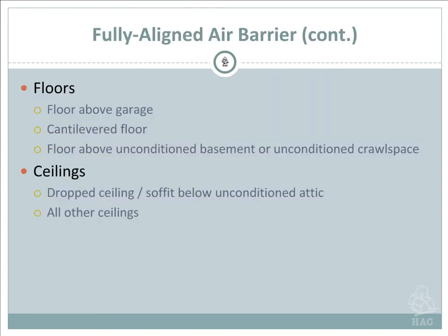Again, floors. You want a fully aligned air barrier on the floor above the garage. Cantilever floors, hopefully everybody knows what a cantilever floor is. These are floors that stick out above and beyond the foundation of the house. Sometimes you can walk underneath them, or people grow plants under there, but it sticks out beyond the foundation and has space underneath from the ground to the floor. Okay. Floors above unconditioned basements and unconditioned crawl spaces. Again, we'll show you a little bit about floors.